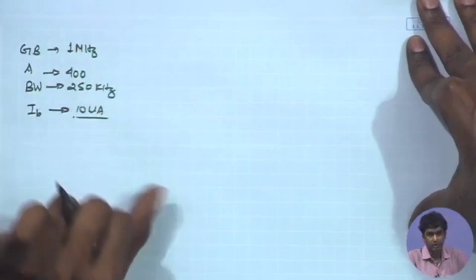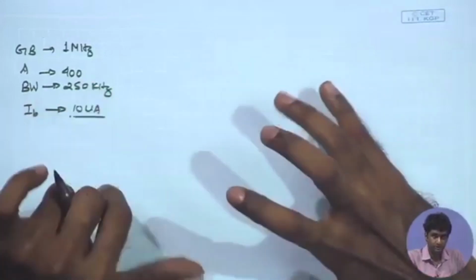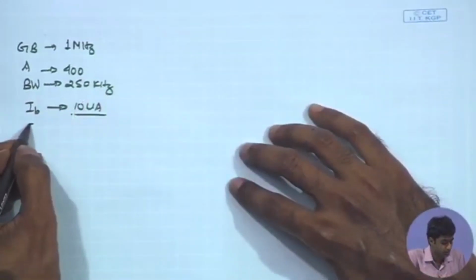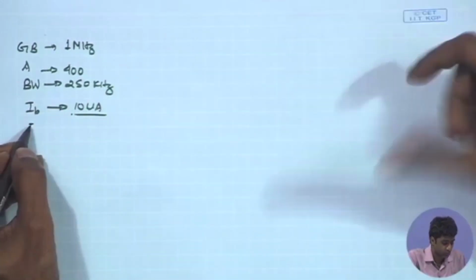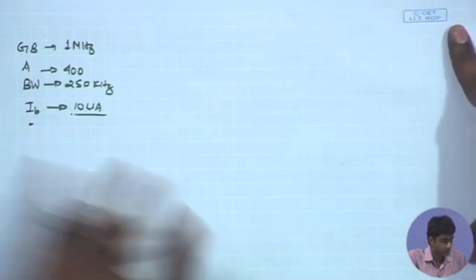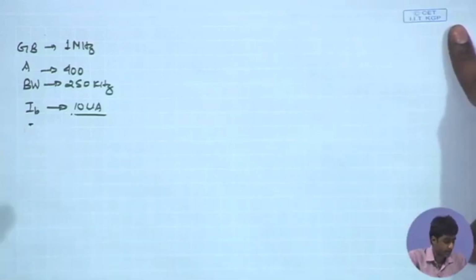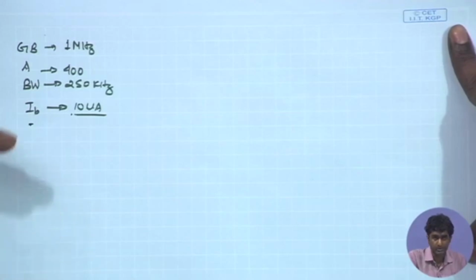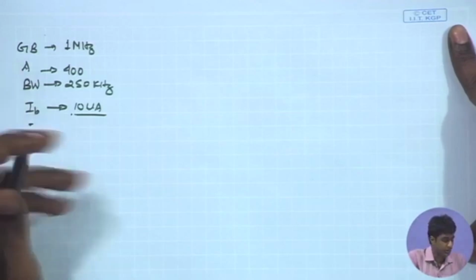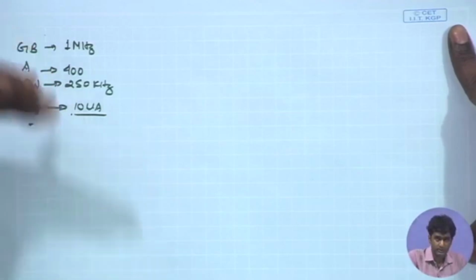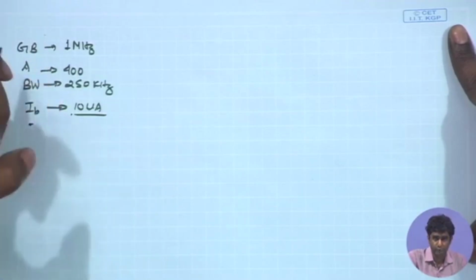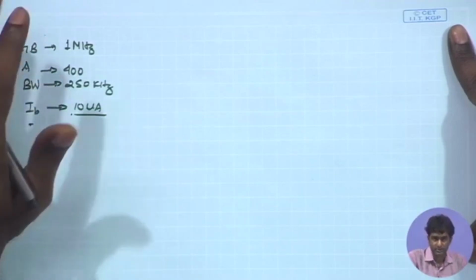Along with that, we also have the constraint of input swing. If you remember, the input swing or input common mode range would be dictated by the maximum peak to peak swing provided by the last stage amplification, and we have seen that it is convenient to get a nearly full swing signal from the last stage amplification.